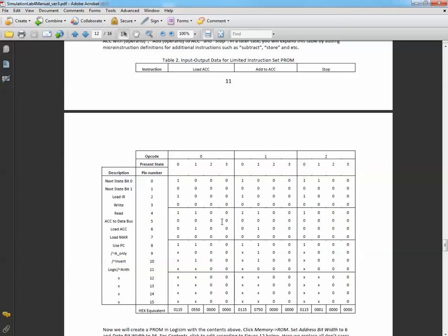The main motive behind this is to let our microprocessor expect some instructions that can be implemented on 4 clock cycles, rather than the load ACC and the add to ACC, which can be implemented in only a single micro instruction, which corresponds to a single clock cycle.